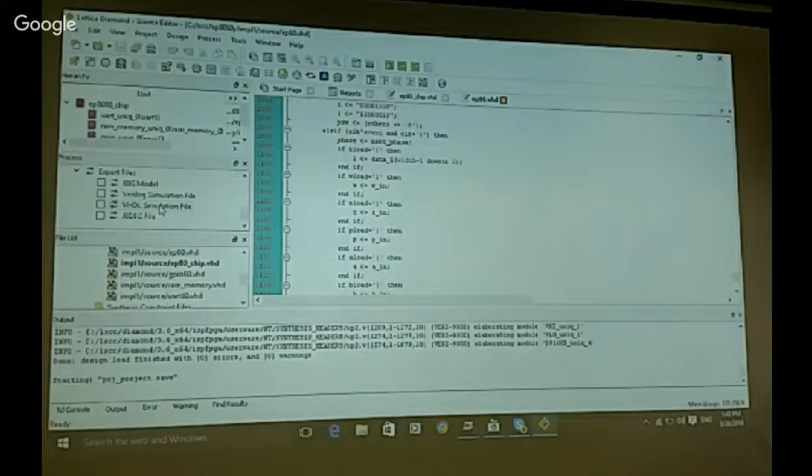You would then skip the synthesis step, just go straight to this VHDL simulation? Yeah, because all the files have been debugged, so basically all the problems have been solved. But if not, it will show lots of errors. When it shows an error, you can try to fix it and then only do the compilation part to do the error checking.